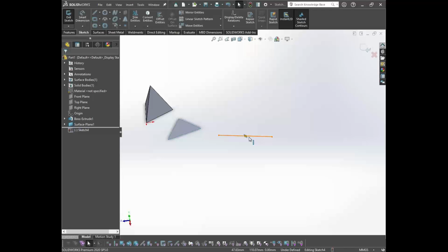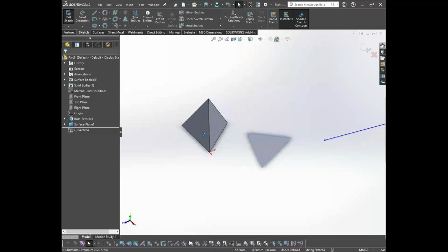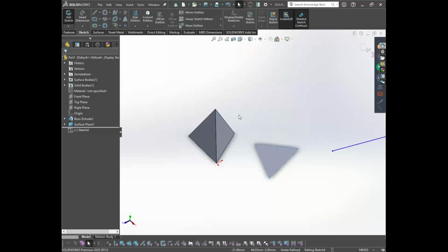During the numerical calculations, it will consider the sectional properties that it has derived from the section or from the cross section, but we won't be able to see it. Why this happens is, you can see here, the 3D solid element or tetrahedral element is 3D in shape. So it requires more graphical memory to process this particular structure.